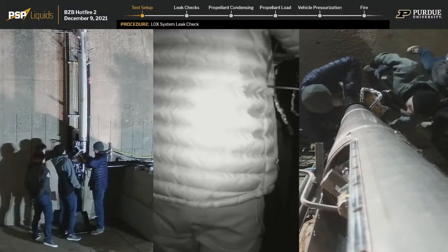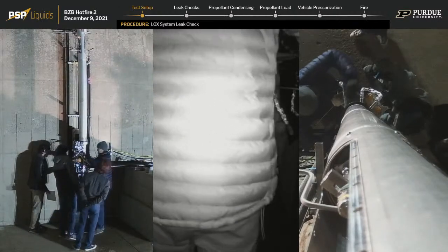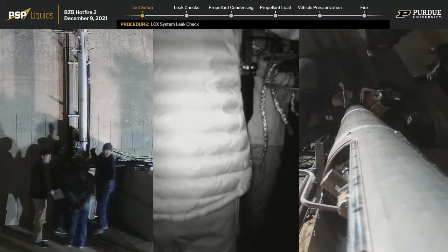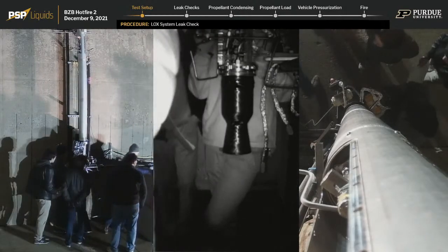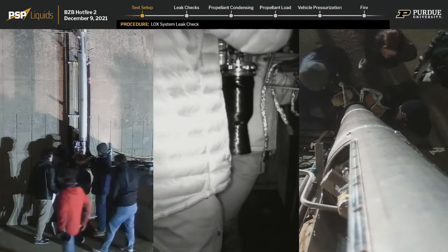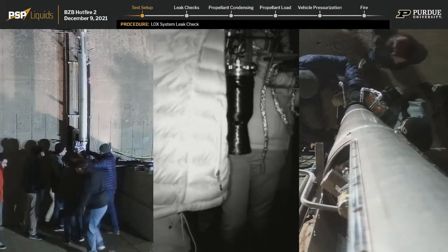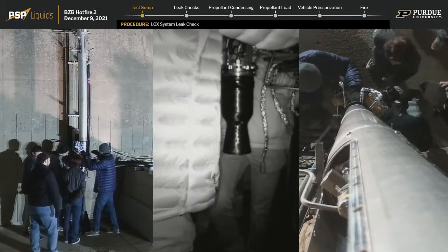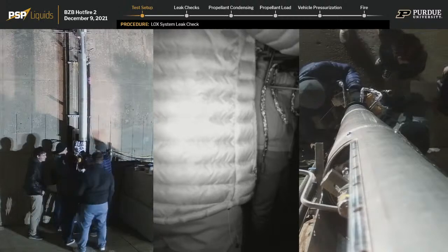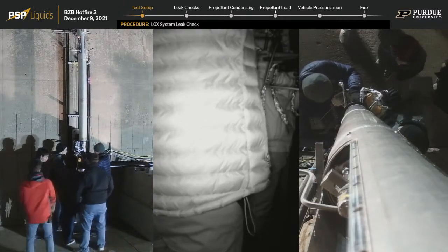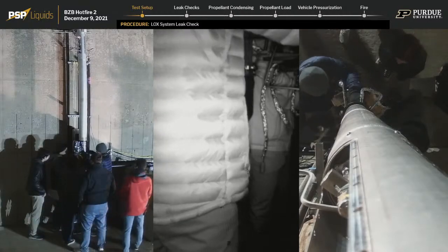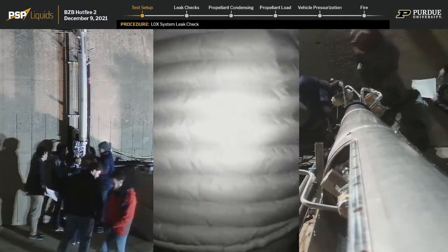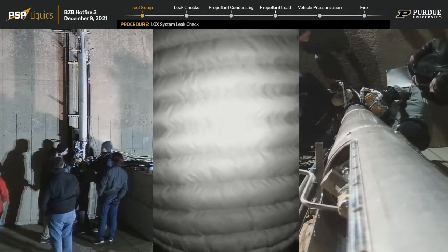So right now we're tightening a lot of stuff in the lower fin can. What is the real purpose of the lower fin can on our rocket overall? So below the propellant tanks, we have an assembly known as the lower fin can, and the fin can houses a number of critical fluid system items, as well as, as the name suggests, mounting points for the stabilization fins, which are not currently installed. So important components in the lower airframe include the run valves. By actuating these run valves, we are able to start up the engine. In addition to that, we have our main method of mass flow control into the engine. These are cavitating venturis.